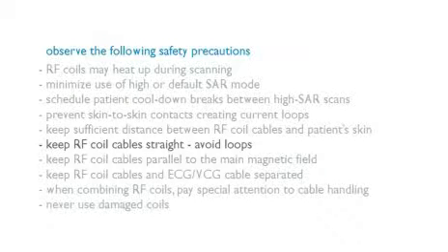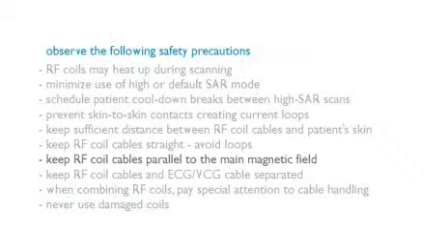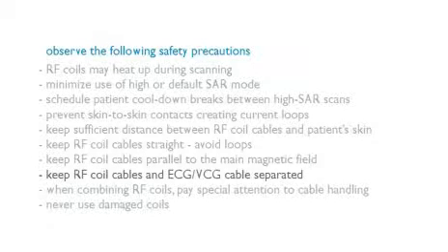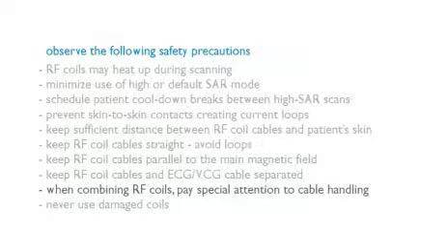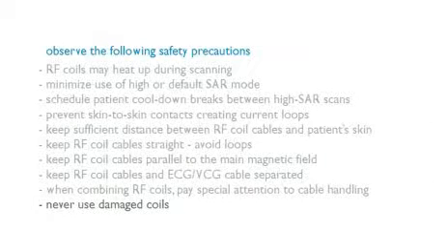Keep RF coil cables straight, avoid loops. Keep RF coil cables parallel to the main magnetic field. Keep RF coil cables and ECG/VCG cables separated. When combining RF coils, pay special attention to cable handling. Never use damaged coils.